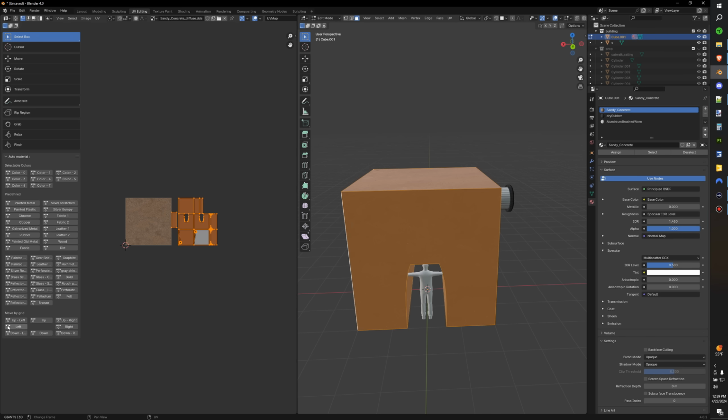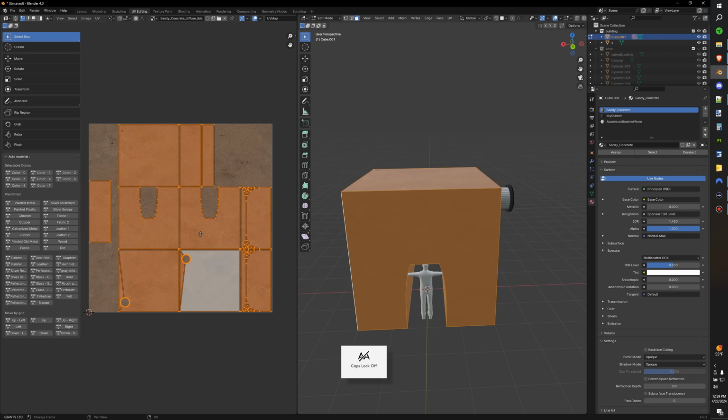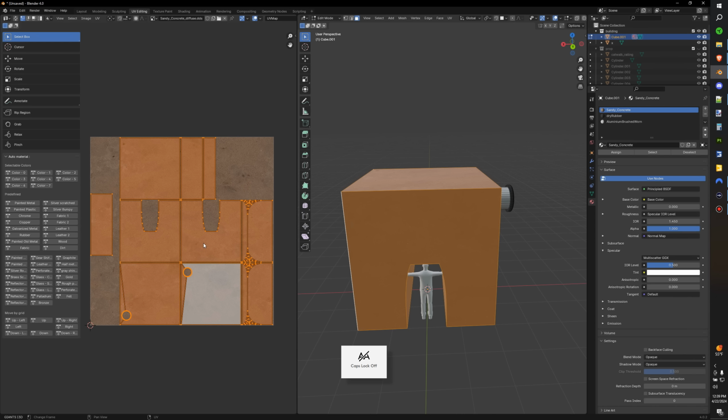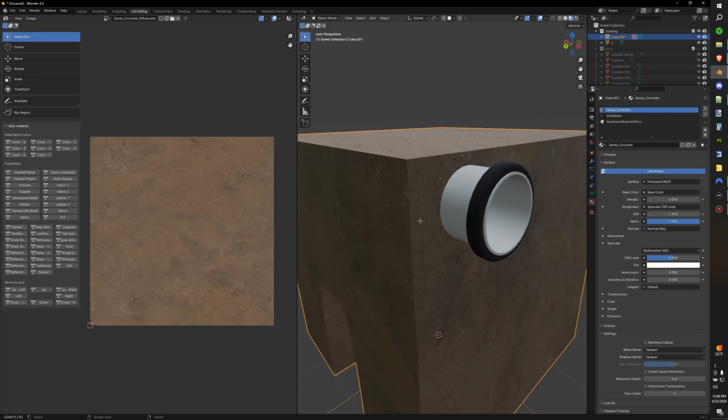So we're going to select our faces, move it down, and here. Now, if you're putting stuff on ModHub, this is not going to work for you because Giants will flag you for it. But if you are just doing this for personal or for PC mods, I like to scale. So to get a better resolution on the texture, we're going to scale it.